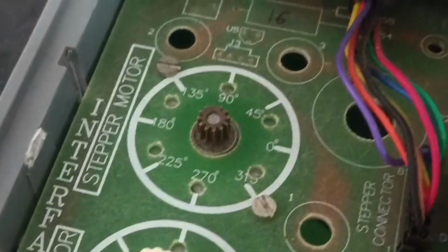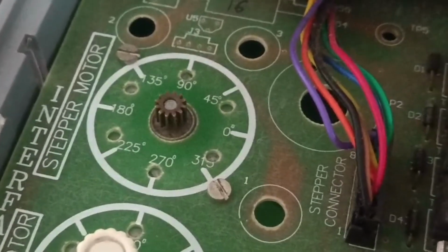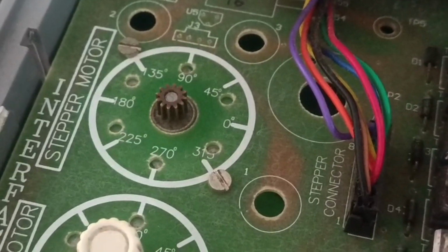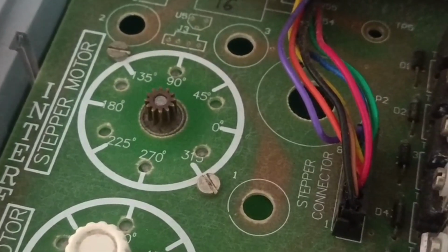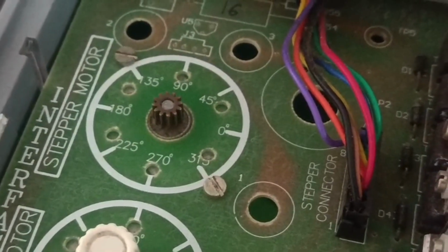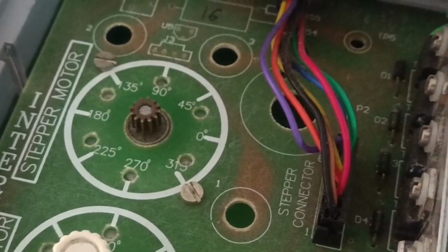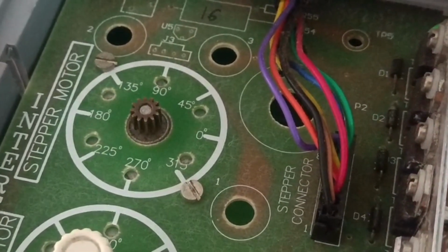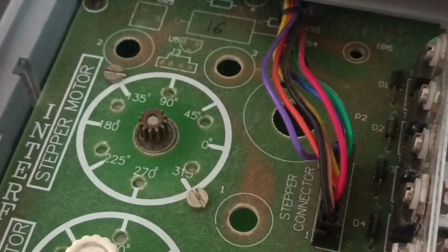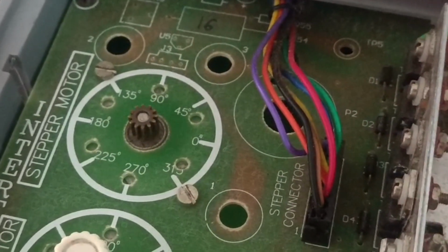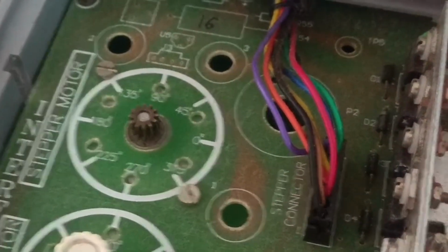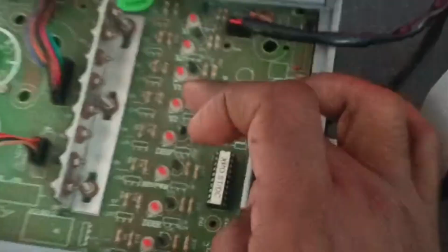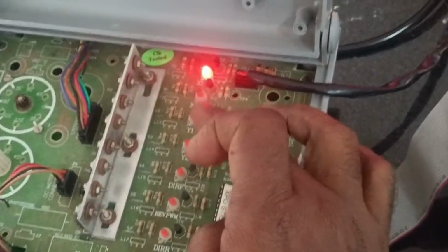So the motor is on. It will rotate in clockwise direction as well as counterclockwise direction based on your program. So it will move counterclockwise. For each step it will rotate 15 degrees. In parallel, the red lights indicate the different phases.